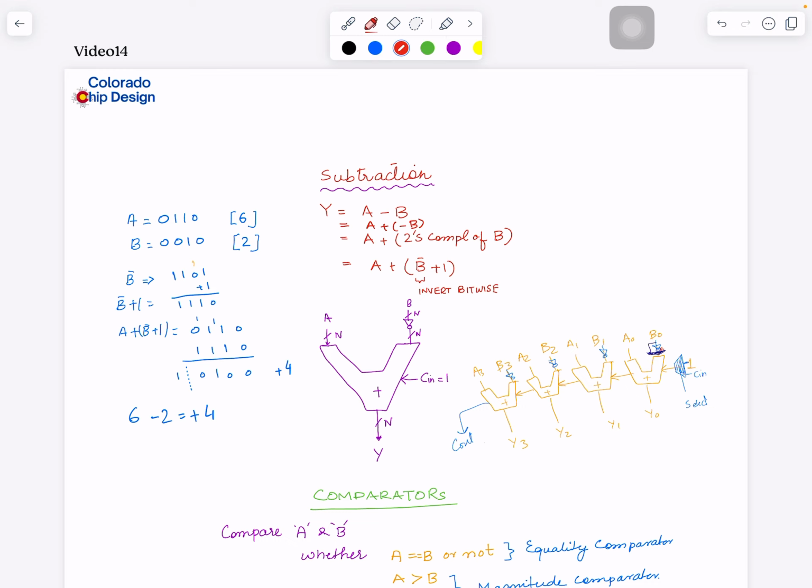So now you are also seeing how those simple circuits, multiplexer and adder, we are using for a completely different purpose here. And that's what this digital design is about. Once you create your basic elements, you can start combining elements to change the functionality of it. And once you select the proper multiplexer input, instead of an adder, it becomes a subtractor, A minus B.